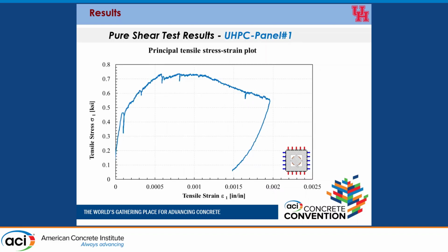Another graph shows the tensile behavior of the UHPC panel compared to the shear behavior. As we can see, we have almost similar curves, because the tensile behavior of the UHPC is governing the shear behavior of UHPC, as we have very high compressive strength of UHPC materials.